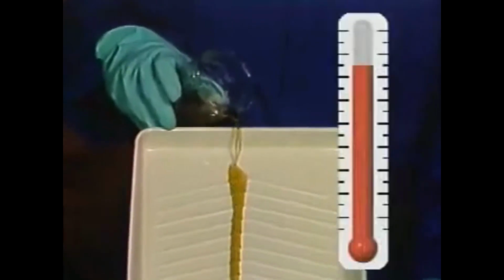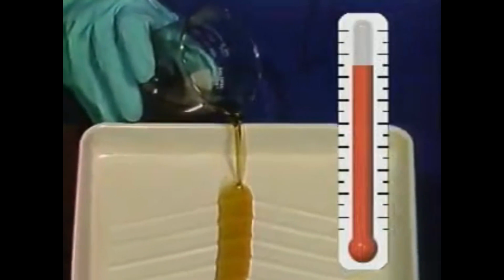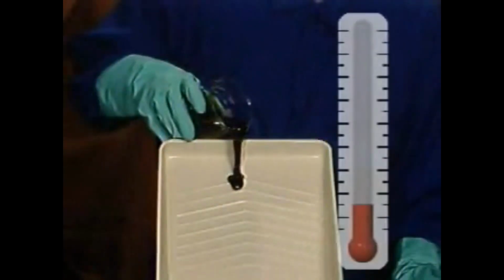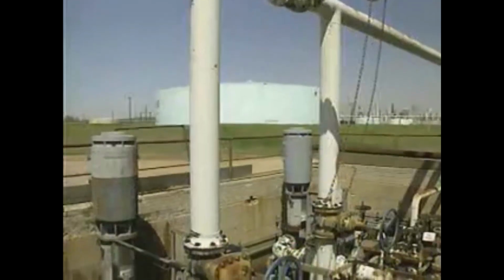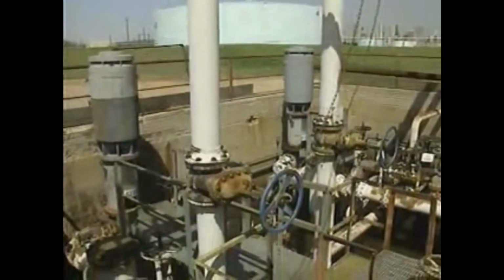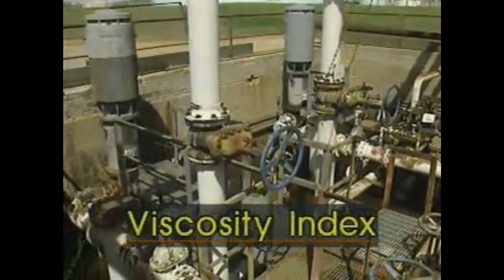Viscosity is affected by temperature. Higher temperatures cause lower viscosity because lubricants thin as temperature increases. On the other hand, lubricants thicken as temperature decreases. Both cases are significant because a lubricant won't lubricate properly if it's either too thick or too thin. If a lubricant is used where large changes in temperature occur, the lubricant's viscosity index is important.